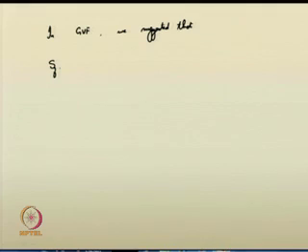In gradually varied flow, we suggested that the friction slope S f has to be computed using Manning's equation, and you have to use the parameters, that is the hydraulic radius as well as the area of cross section at that particular section. Whatever the corresponding values of A and R are, you have to substitute them and identify the friction slope. So, this was given in the following form: